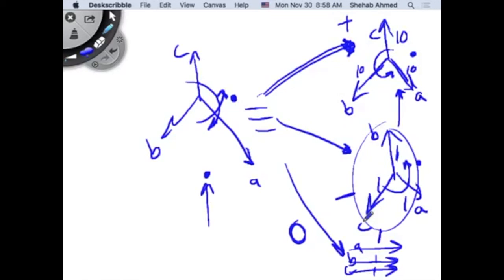DC braking, plugging or DC braking, right? So this is like DC braking. You're putting DC, and DC is what? DC is one value of voltage in space. Is it rotating? No, it's not rotating. It's a voltage where all three voltages are in phase.